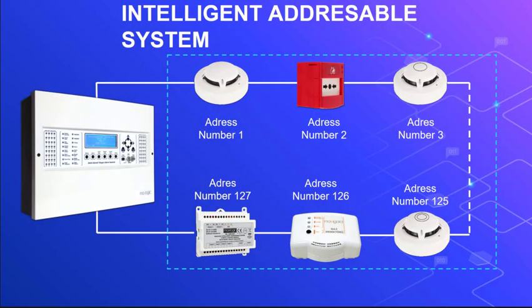If we look at the smart addressable systems, values such as the building construction area, the height of the building, and the number of users grow and the buildings become architecturally complex. The emergency risks of the building should be analyzed immediately after the architectural project is created. In order to evacuate the people living in the building and to provide maximum living conditions in an emergency, needs should be determined and emergency scenarios should be developed. After risk analysis, determination of needs and emergency scenarios, the fire alarm system should be designed.